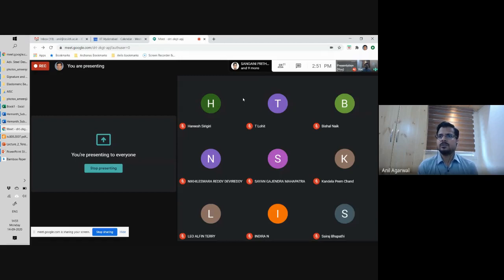The strength limit states will be the ones which, if exceeded, then I will not be able to use that building again, because the building will have a significant permanent effect. Okay. Or the structure, not just the building, any structure. So basically these kind of limit states could have various types, at the material level or at the member level, you may have various aspects or various manifestations of that kind of limit state.